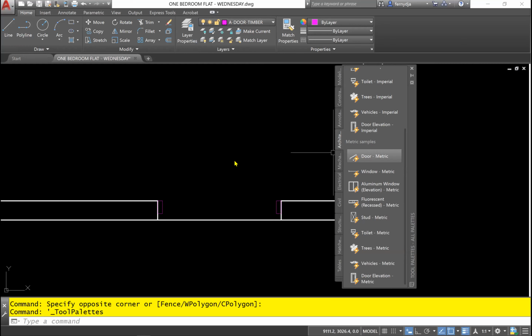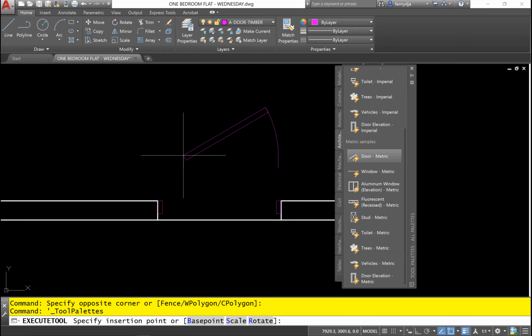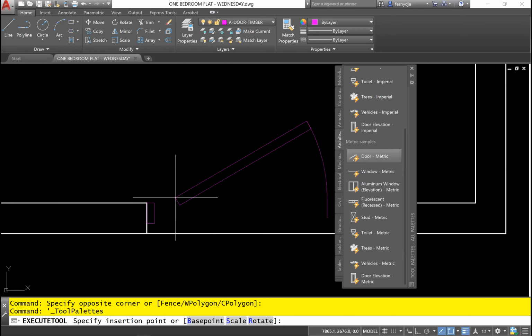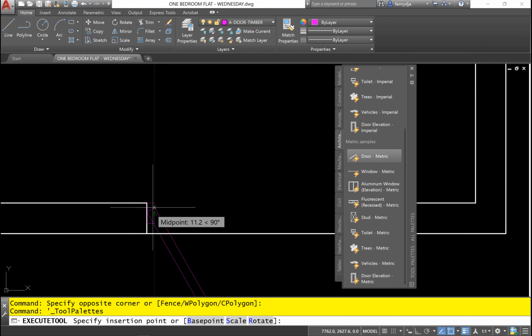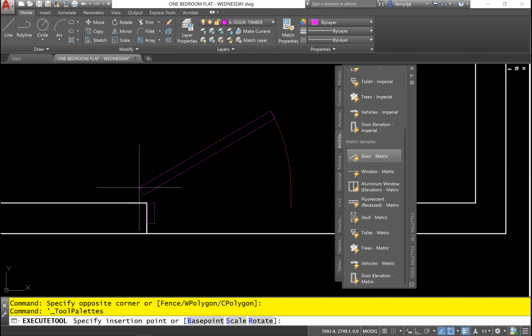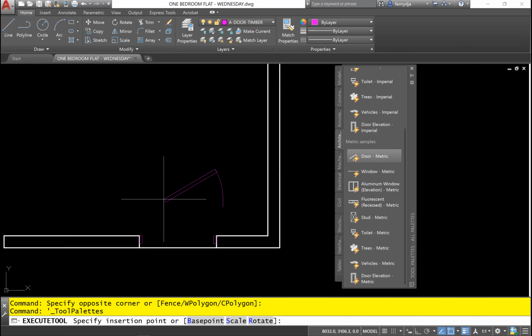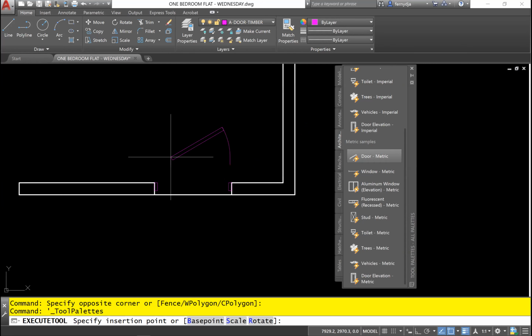Notice when it comes out on your cursor, you will see it is actually on the left side as if it's a left hung door. No problem. The reason why I'm not going to try to put it in place is because when you try to put it there, it starts to flip all over the place. Why? It's trying to align itself on the vertical, and it's also trying to align itself on the horizontal. So when it's time to put on a vertical surface, we will just be able to do that quite easily. So I'm not going to fight it.